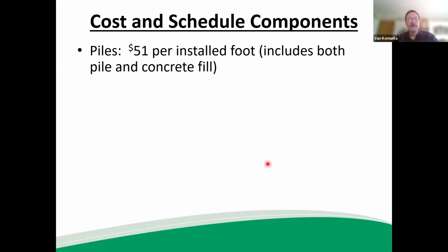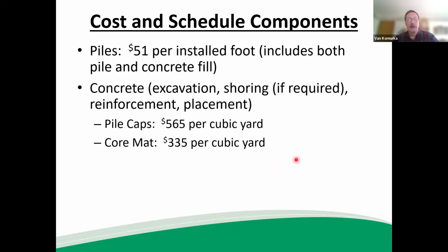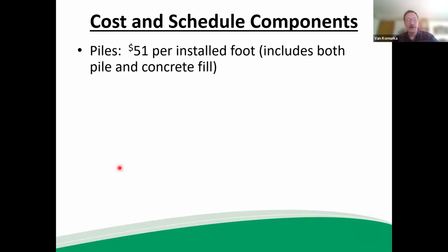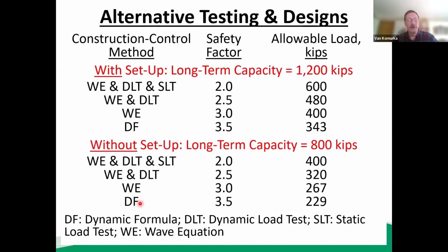Cost: $51 per foot. And the construction management team was very cooperative in giving these costs. Concrete excavation, pile caps, or mat, different placement costs for the concrete. Construction control methods, in other words, from dynamic formula to what I would call a full boat test program with restrikes and instrumented static load tests.